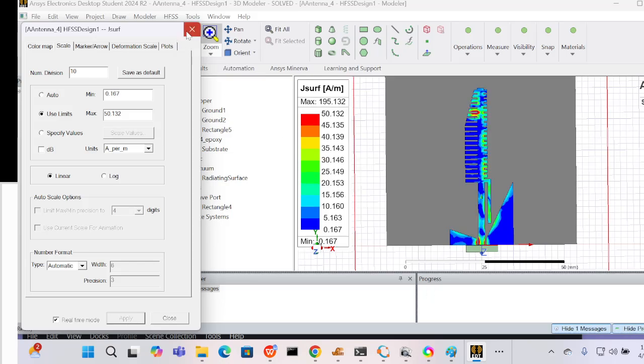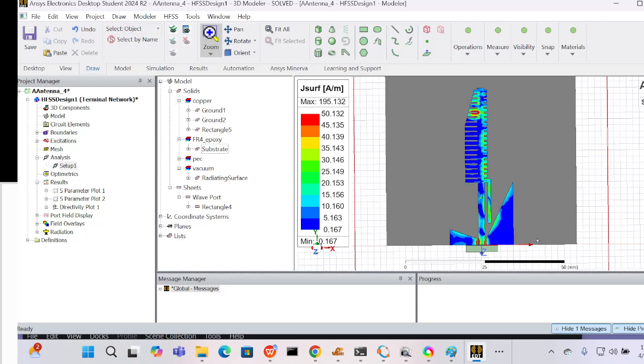So you can clearly see how the surface current densities appear in the final design. And surprisingly, the surface current density at this region is comparable to the surface current density at the input port. Perhaps this is the main reason you end up with the maximum magnetic field there, and how you end up with end-fire radiation from this antenna.